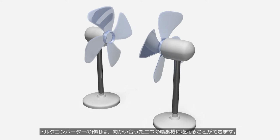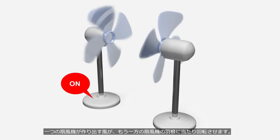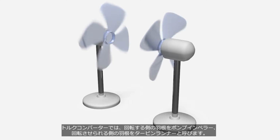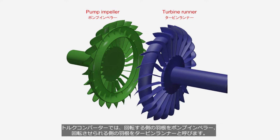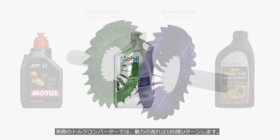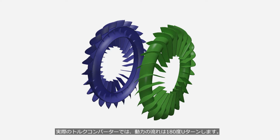The function of a torque converter can be likened to two electric fans facing each other. A fan generates airflow, and it hits and rotates the blades of the other fan. In a torque converter, the rotating blades are referred to as the pump impeller, and the blades that are rotated are called the turbine runner. The medium for transmitting power is not air but oil, and this oil is referred to as automatic transmission fluid, ATF. In an actual torque converter, the flow of power makes a 180-degree turn.